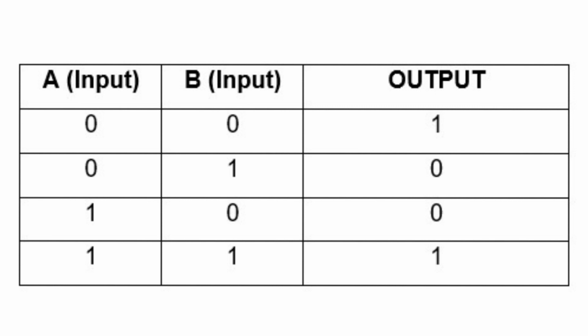In the data gathered, it can be seen that there will only be an output of 1 whenever both the inputs have values of 0 and whenever both inputs have values of 1. This is because the logic output of an XNOR gate is the complement of the XOR's. Thus, an output of 1 is observed whenever its inputs are alike and 0 if not.